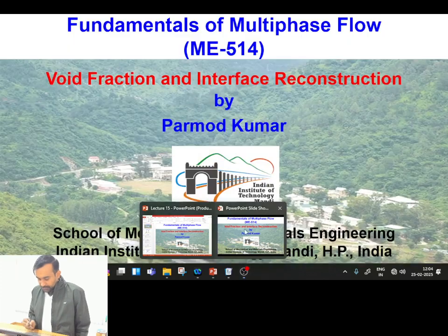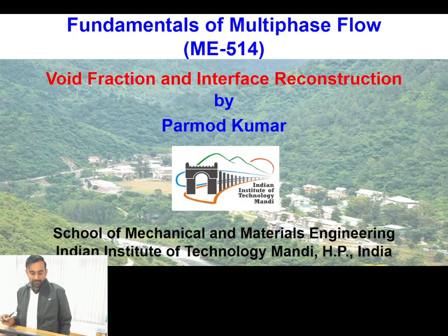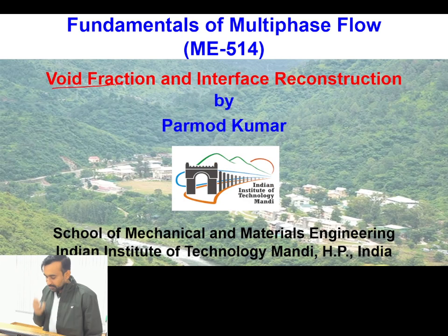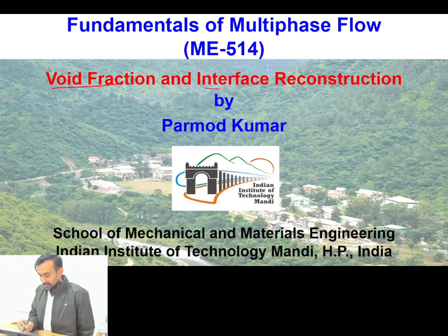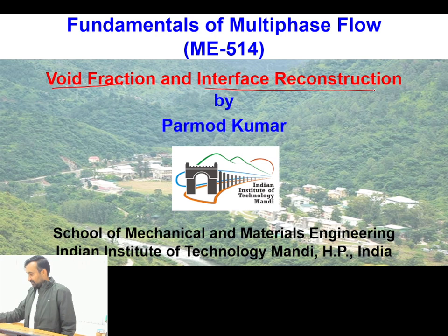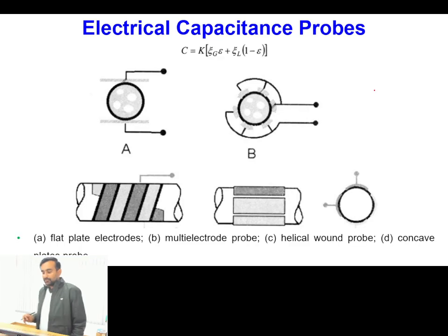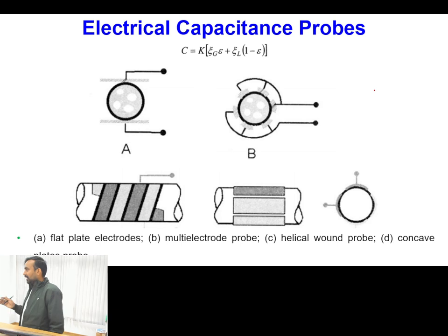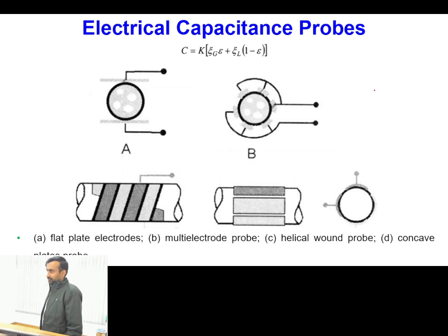Okay, good afternoon. We will continue our discussion on measurement of void fraction. After that, we will shift towards the interface reconstruction techniques. In terms of void fraction, we have mathematically seen that we can classify it as one-dimensional, two-dimensional, or three-dimensional. And in terms of the measurement techniques, we have to know the phase density function. If we know the phase density function, then we can easily estimate the value of the void fraction.